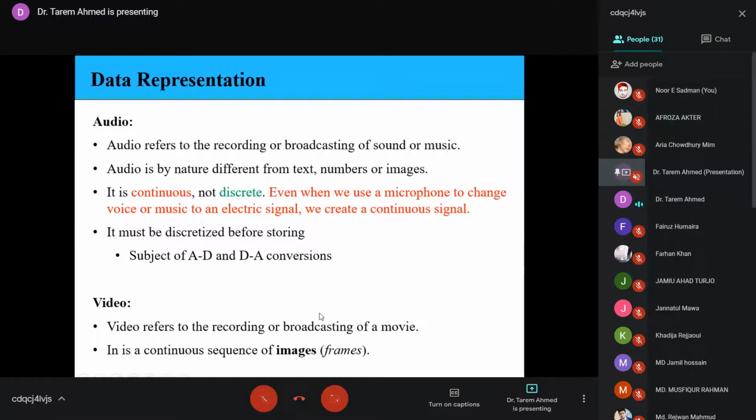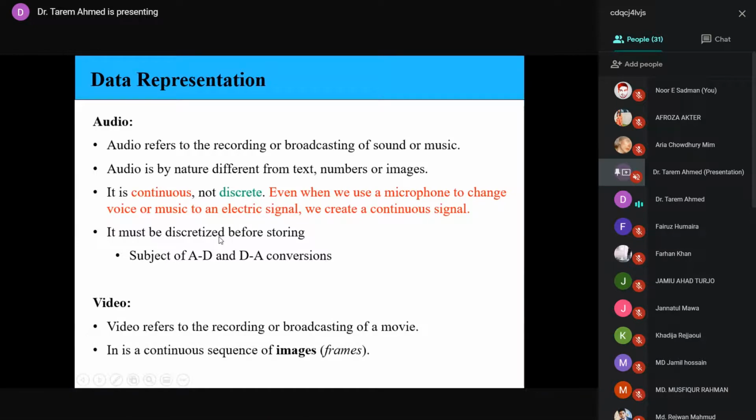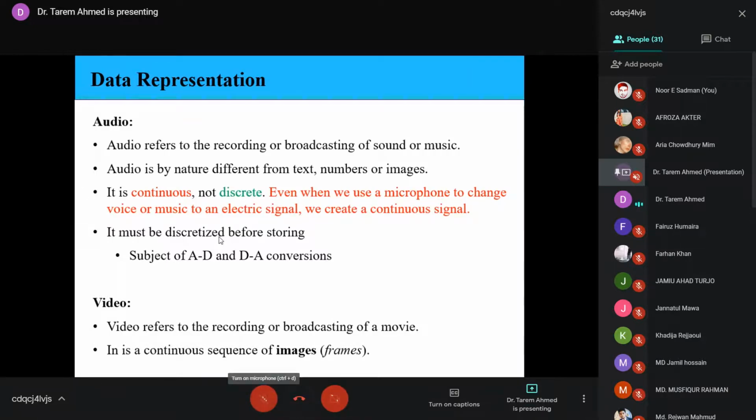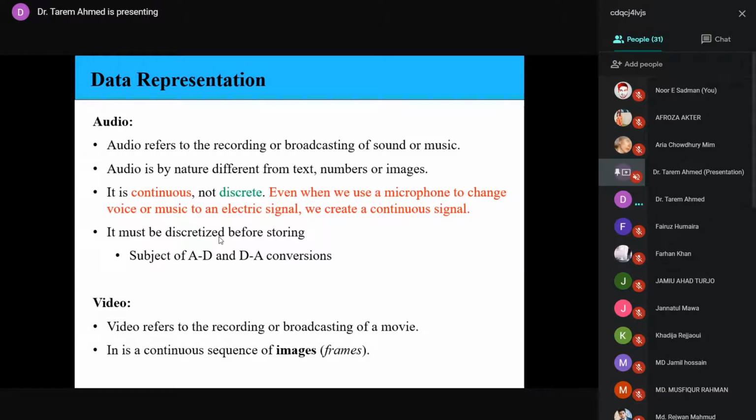So the obvious question is, why do you convert to digital? The answer is that there are many different reasons. In an electrical engineering class, I would go into more detail, but here, just for curiosity's sake, digital is less susceptible to noise. An analog signal is more susceptible to noise. In a digital signal, it is easier to identify and remove noise. In an analog signal, that is not possible. Also, data compression is easier in digital. Ciphering and deciphering, encryption, is easier, or possible, in digital.